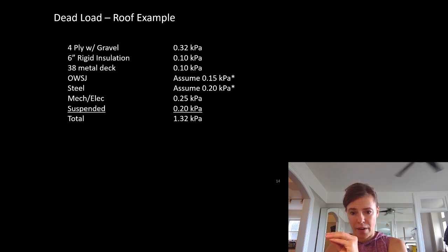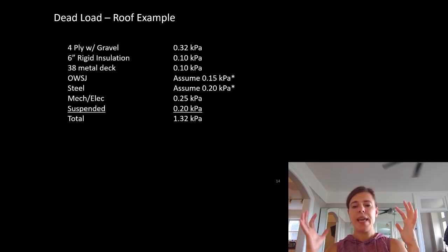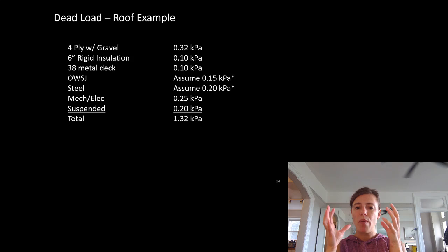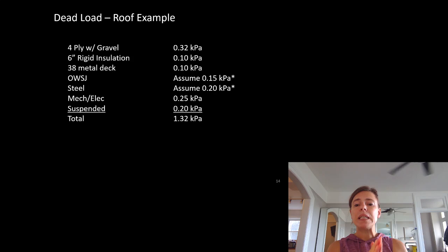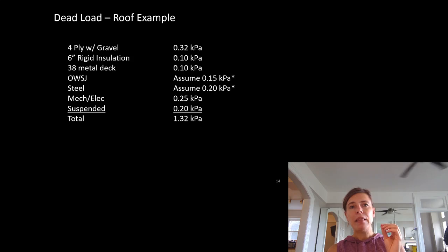What we assume here in our design is that we take all that steel, it's not literally what we do, but the way we think about it is we take all that steel, put it in a blender, turn it into a spread, and spread it out all over the floor. So we're basically assuming the weight of the steel is distributed evenly everywhere on the floor. We know that's not true. In high load or very specific cases with very large members, we might not follow that approach, but most of the time it's a pretty good way to do our calculations.